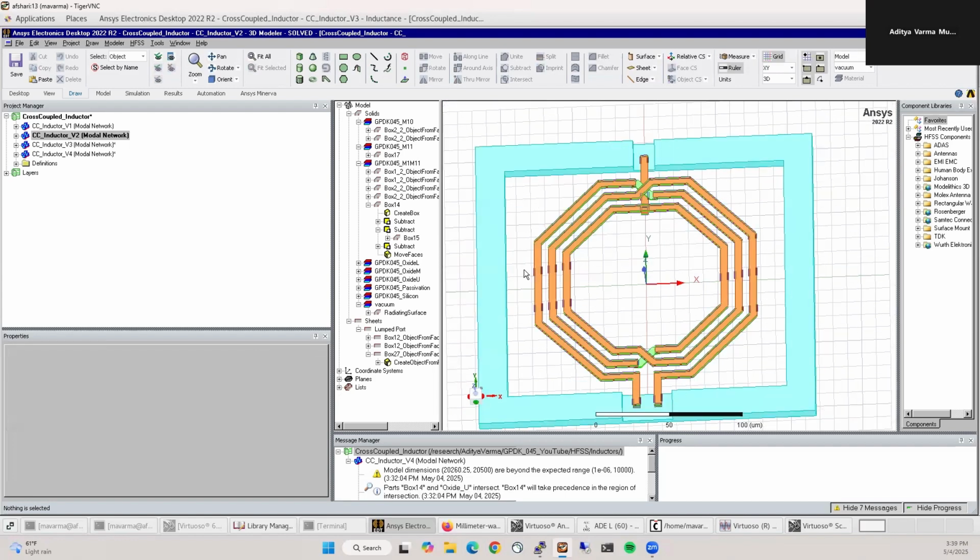Okay, with this simulation, you can't find the inductance because you can't really use the Y parameters of just a two-port network. It's a three-port network. So just make sure that you keep that in mind. So this is just to extract the S parameters, right?